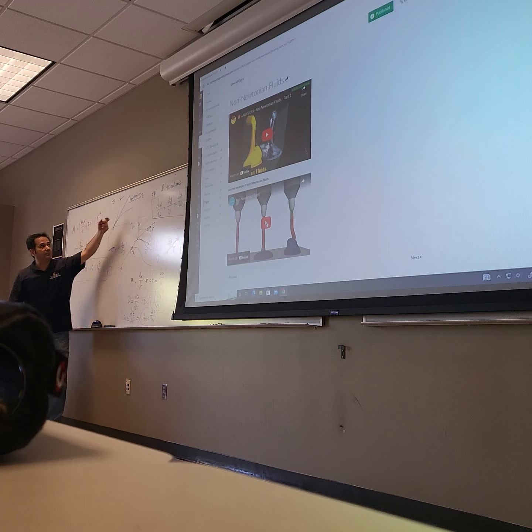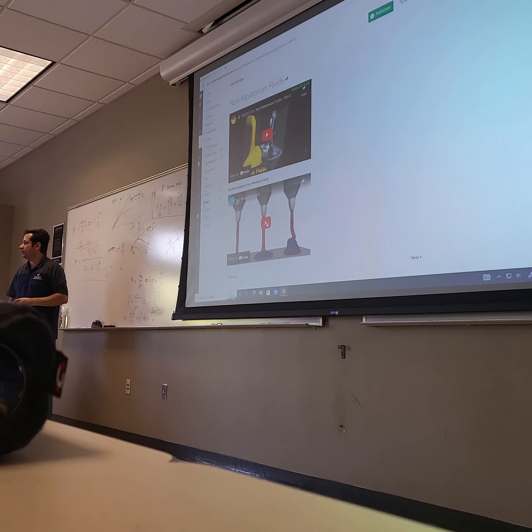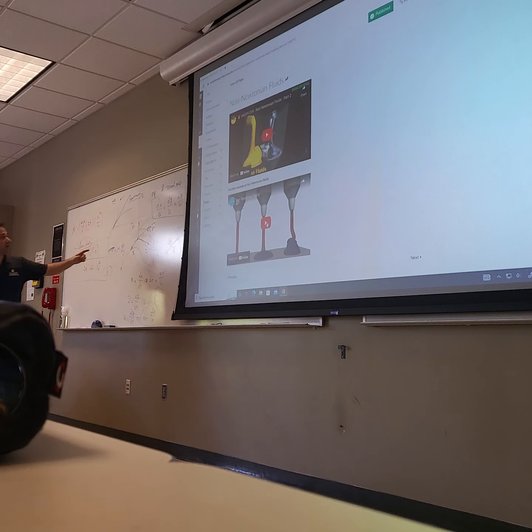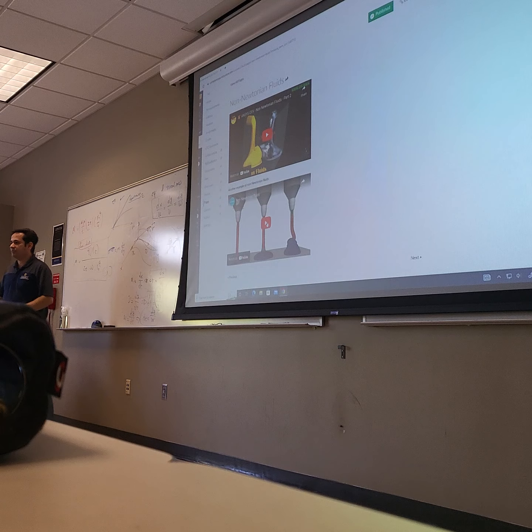But both of them, sub-Newtonian and super-Newtonian, they call them non-Newtonian. And all they do is make your integration harder. You see how beautiful it was with the Newtonian case? We used easy integration to find the relation between torque and viscosity. That was very easy. These guys make the mathematics really nasty.